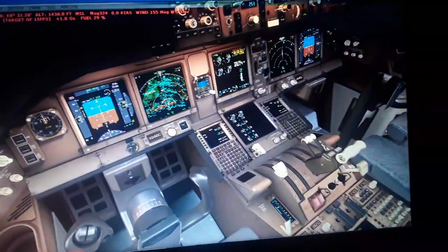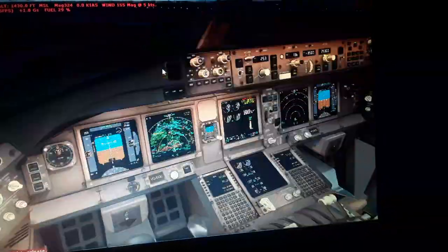for symmetrical thrust and redundancy. So you can use variable thrust, you move the thrust levers in different positions. The FADEC can also control and modify the N1, which is the low speed, low pressure compressor and turbine, the low speed shaft and rotor of the turbofan engines.